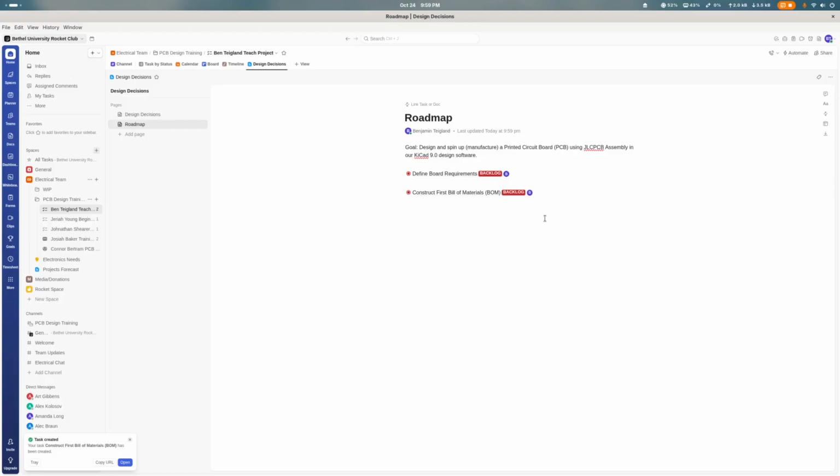Secondly, you could design with generic boards, say, I'm going to do a sensor that has this footprint and I can wire it up with these things. You could do that. I wouldn't recommend it. I don't know if anyone does it, but you can, especially with some boards. The drawback is, if we're using this assembly, we don't know if JLC PCB has the part. We need them to have the part in order for them to manufacture it.